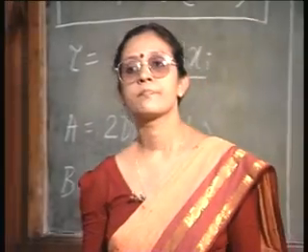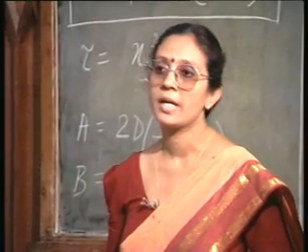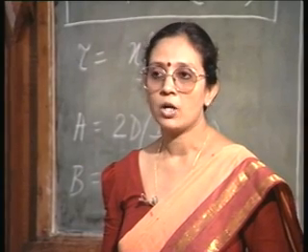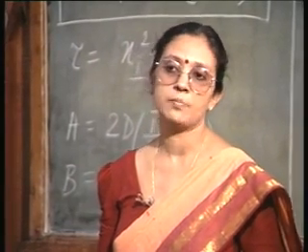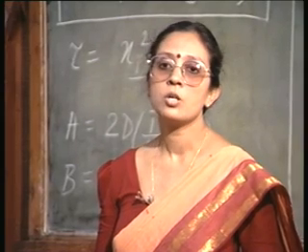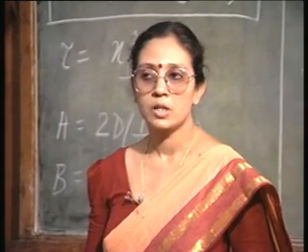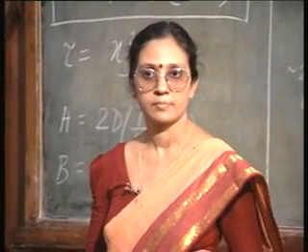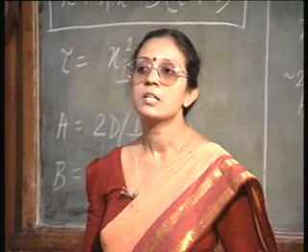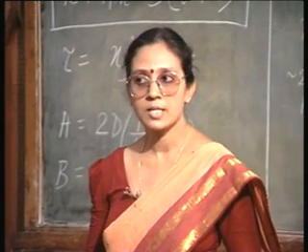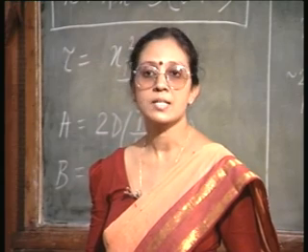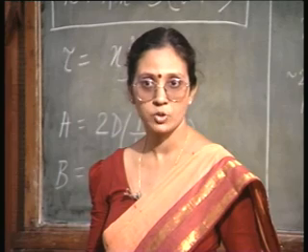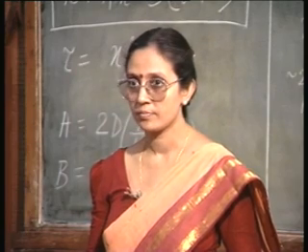This is because when we are talking about a heavily boron doped sample, the oxidation rate is faster because boron converts the oxide into borosilicate glass, and diffusion of the oxidizing species is faster through this boron doped silicon dioxide, which I am calling borosilicate glass.